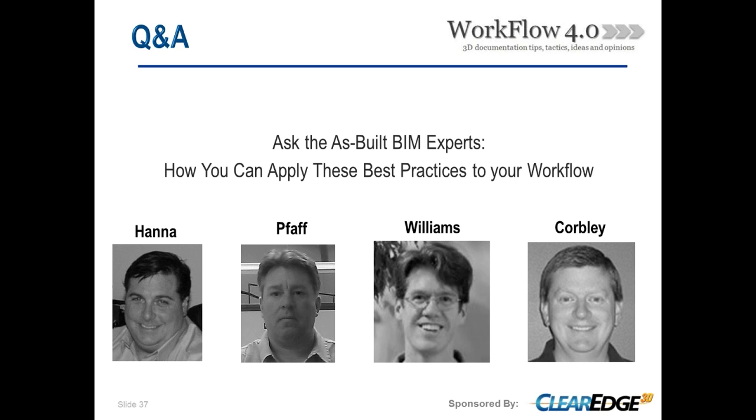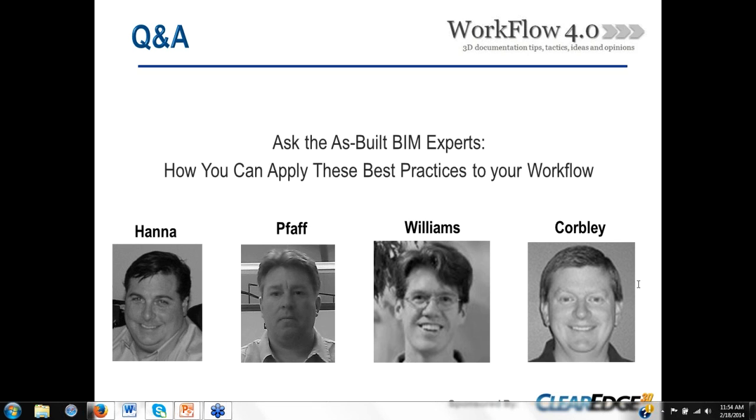The first question that I've got is for Mike Path. Did the client define the level of required tolerance for the geometry in the model? Yes, they did. They're looking at a 1/2 inch or less, which is one of the reasons we took the reflectorless shots throughout the facilities to identify and show the consistency of the cloud data against the traverse data.